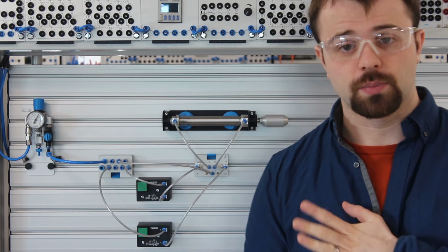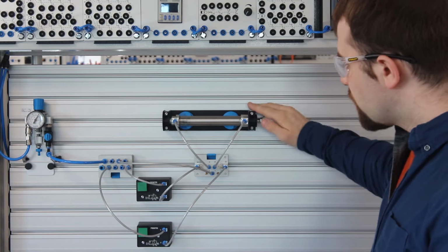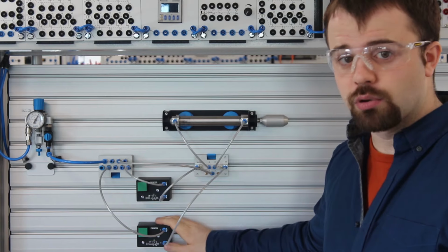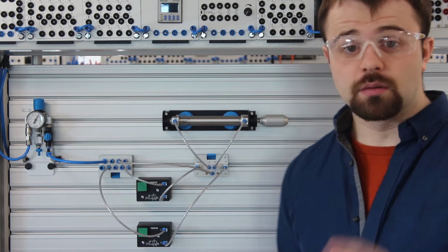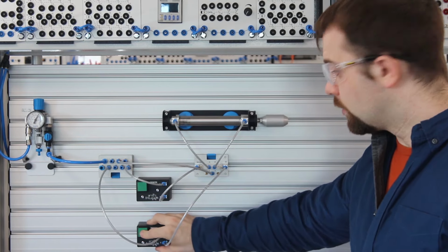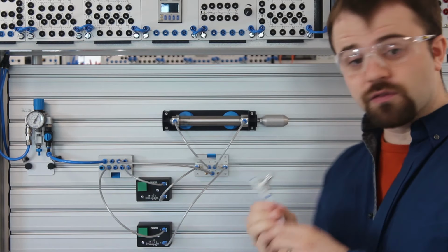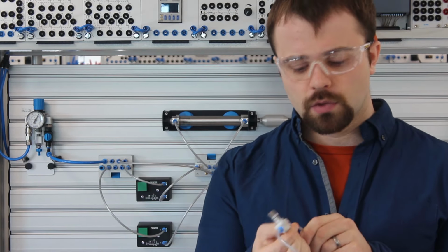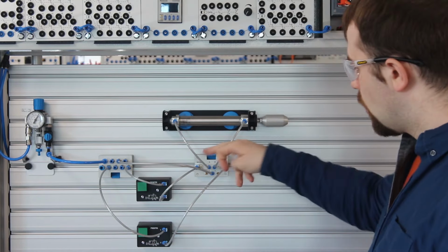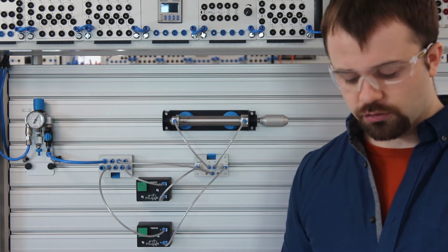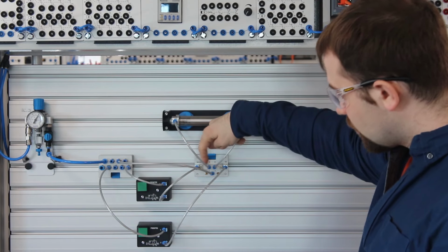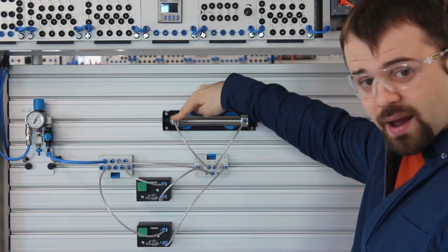Okay, so I've zoomed in a bit so this bit is a little bit easier to see. What we've got here is a double acting cylinder, a 5/2-way valve, and then two 3/2-way control valves with buttons on them. This is the system that we had in one of the previous videos, where we have the top button to go out and the second button to go back again. What we're going to do is fit one of those flow restrictors that we just looked at. You might think, because of the way that the restriction goes, the best way to put it would be on this end of the cylinder. Let's try and do that first. So I've got the arrows pointing towards the cylinder, so we're restricting the air going from 4 into the back of the cylinder.